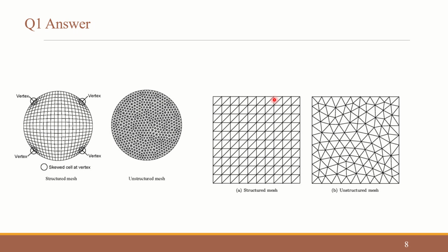When we are talking about mesh refinement in this particular zone alone, we will divide it further. But since this is a structured mesh, the division will be carried over the entire thing. I mean, here it will be refined, here it will be refined as well.